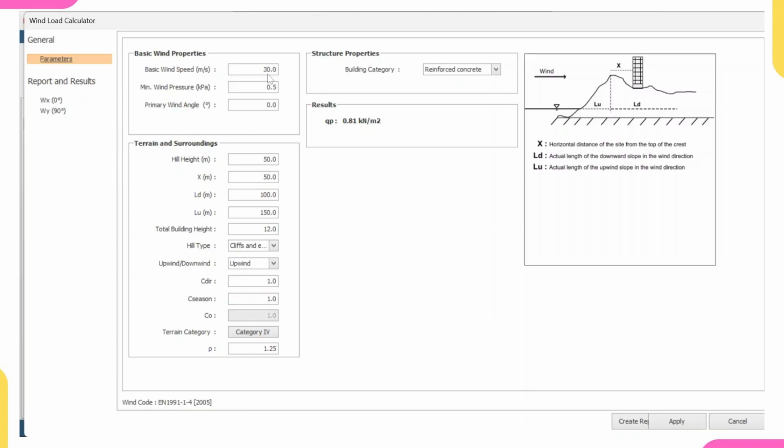But if you want to get the wind speed of your area, you'll browse the wind speed of that location in the last 5 years. Once you get it, you then take the average. Don't go beyond, don't go back 20 years or 30 years, because 30 years ago the number of buildings in that area may have been few, which means the wind speed would be very high. But recently development has started entering that area, so there are more buildings now, and those buildings will be restricting the wind speed. That's why you should just take from now to the last 5 years.